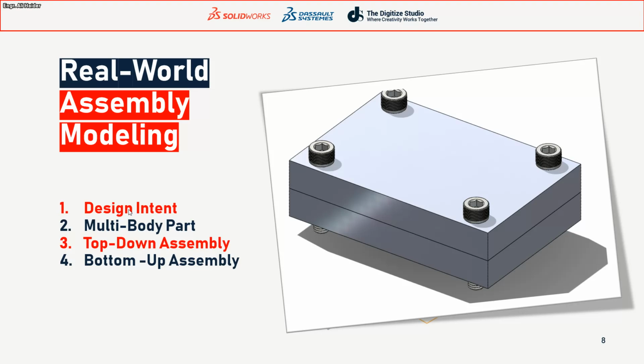So this is the design intent. In this way, you have to organize your feature tree so that you apply the feature at the very first stage, and then we move with the same intent until we have our final design. A perfect design intent CAD model is one where, if you want to modify the design, you just need to modify one thing and everything will be modified accordingly.